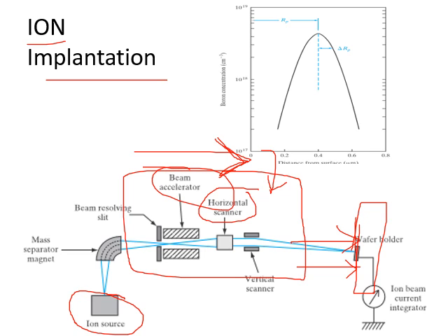The ions are projected and incident on the wafer with a very high speed. Because of that high speed, the ions diffuse inside the substrate or the semiconductor. So ion implantation is an alternative to the very high temperature diffusion process.